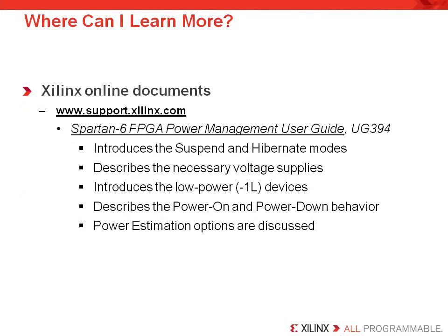Well, there are lots of ways and lots of places to learn more about FPGA power consumption, and they all start at support.xilinx.com. In particular, I want to point you to the Spartan 6 FPGA Power Management User Guide. This discusses a lot of the concepts we discuss in the other recorded e-learnings on power management, including introducing some of the newest features such as suspend and hibernate modes, and describes the necessary voltage supplies, describes the low power devices that are available to you, and describes power on, power down behavior as well as power estimation options. So check it out.